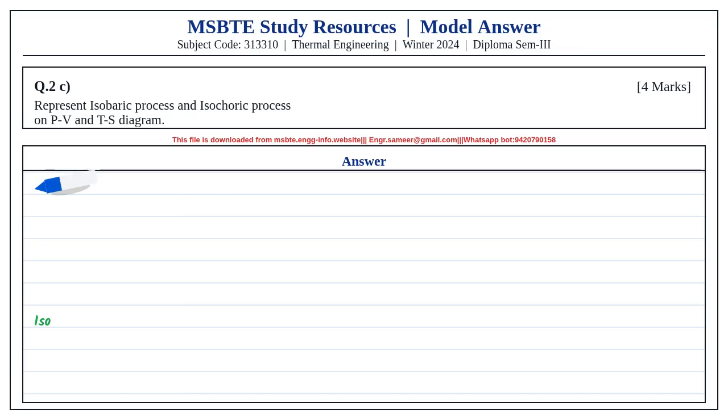Question 6a. Differentiate between impulse turbine and reaction turbine. The table shows differences between impulse turbine and reaction turbine. In impulse turbine, steam completely expands in nozzle and pressure remains constant during flow through blade passage.